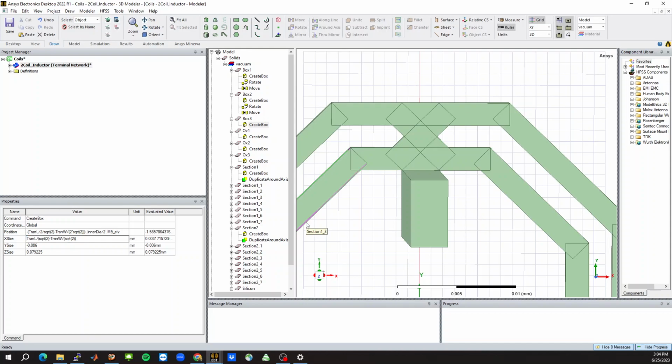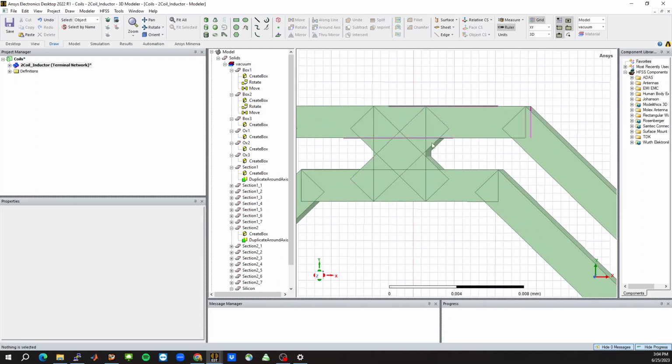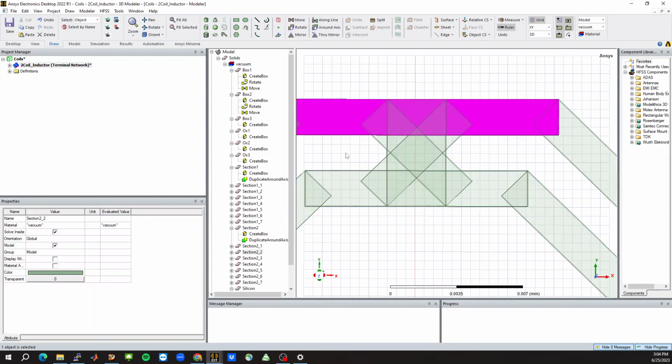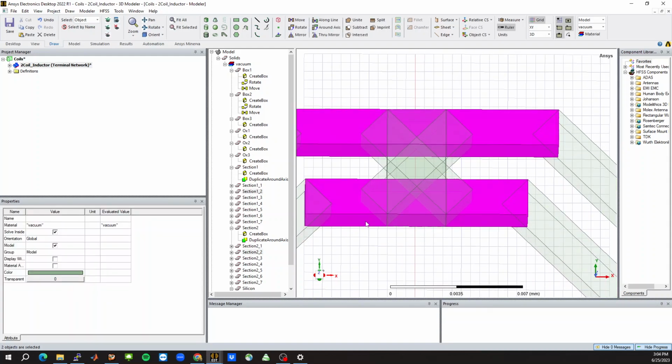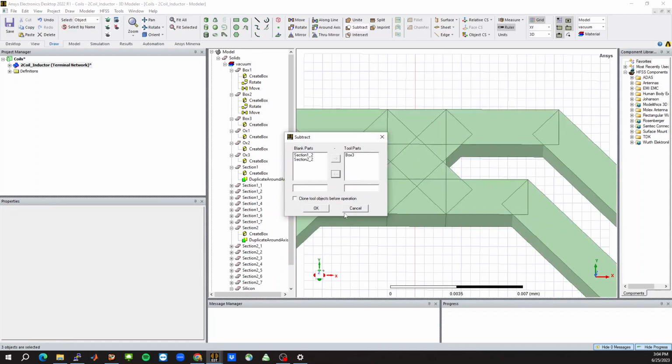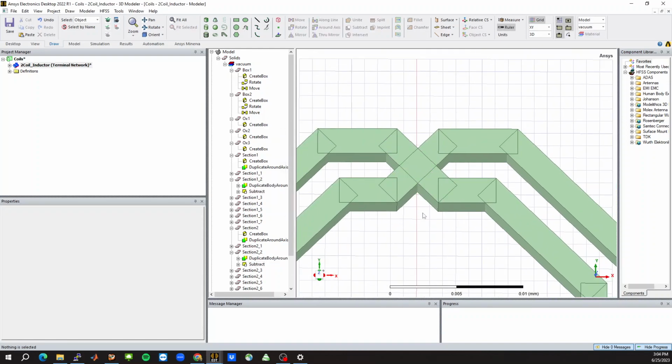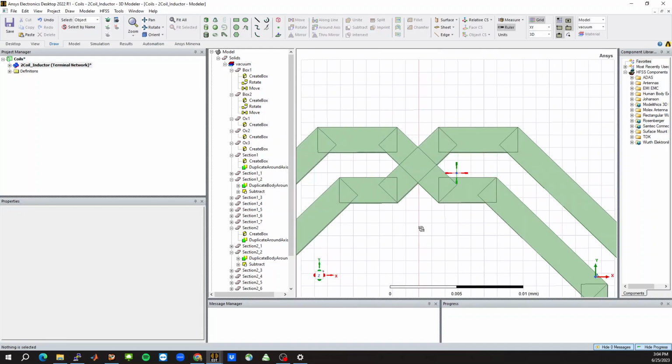Okay, we need another bracket here. And this should be 2 times line width plus gap and M9 thickness. Okay, so now you see that we've made a box that exactly touches these 4 points. The next step is to select both of them, and also select the box and subtract. But you only want to subtract the box from these 2 sections. So now we end up with a transition that looks like that.